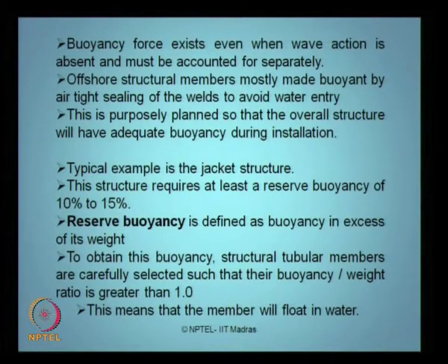Let us take a typical example of a jacket structure. The jacket structure requires at least a reserve buoyancy of about 10 to 15%. Now the question comes, what do you understand by reserve buoyancy? Reserve buoyancy is defined as the buoyancy in excess of its weight. To obtain this buoyancy, structural tubular members are carefully selected such that the buoyancy by weight ratio is always greater than 1. It means buoyancy will always be greater than weight.